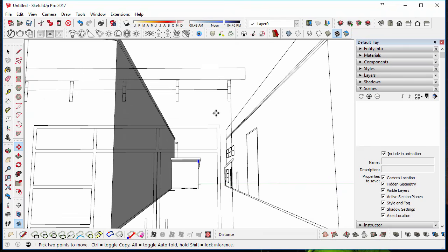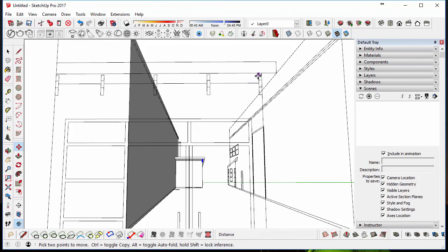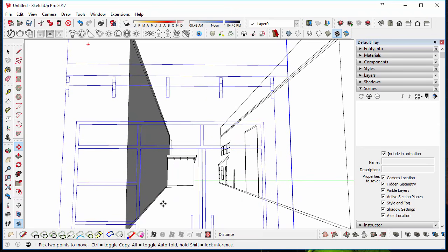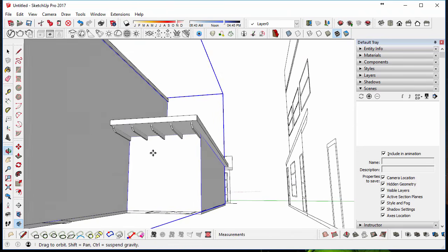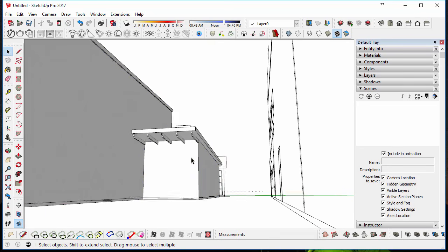And you can see here on the other elevation down the other end that we've got some details of that. I can now copy from this point using the move tool and control to this opposite side and click. And there's 4 divisions, so I can go 4/enter, and if for example you got that wrong, which I don't think I did, but if you did, you could say, okay, maybe it's 5/enter. Okay, that's too many, so we'll go back to 4/enter, and you can just keep modifying until you change tools.